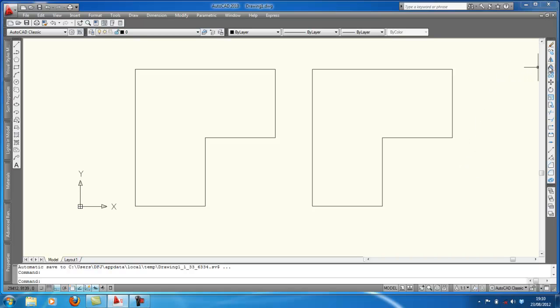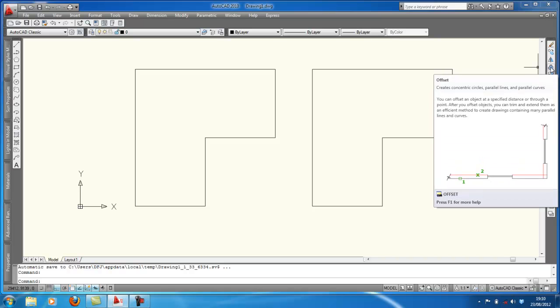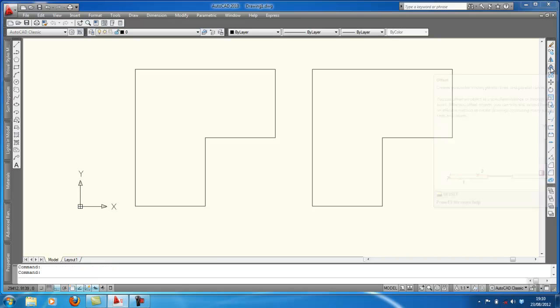And there is the offset command. As you can see, it says offset. It looks like a little cloud, right? So click on there, and one of the first things that it says right there on the screen, it says specify offset distance or a point. Okay, I will specify 100 millimeters. Enter. Now, can you see that your target cross is changed into a little square?